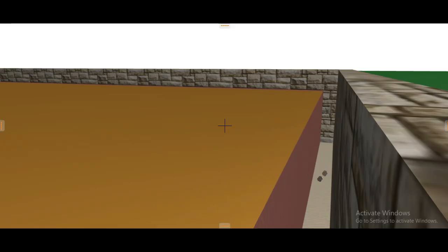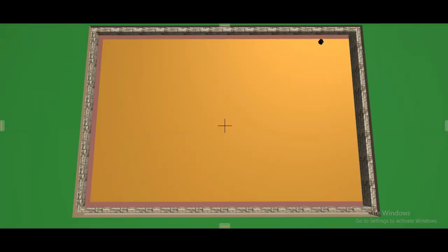So when I have to enter this one in the squaring column, first of all, I get the mean gap all around, and it is 37.60. And that 37.60, I derive it from the center line, that is between this edge and this wall.